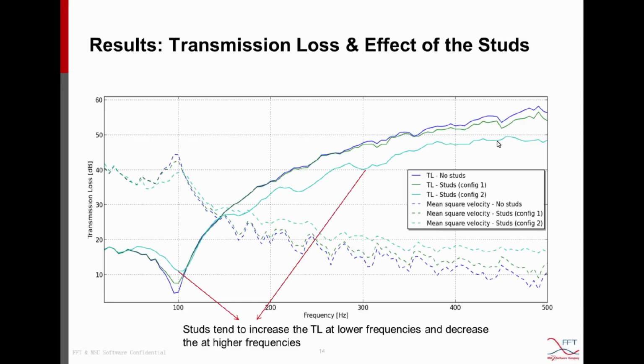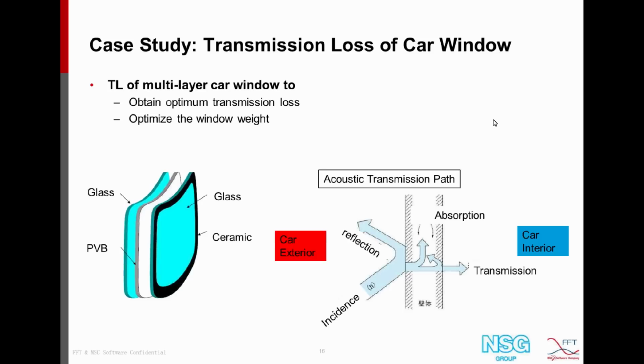So consequently, the vibration of the transmitted part of the plaster will be amplified because of that connection, and that will bring down the transmission loss, as we can see here at this higher frequency region. So this is the example that we walked through on this typical wall partition problem.